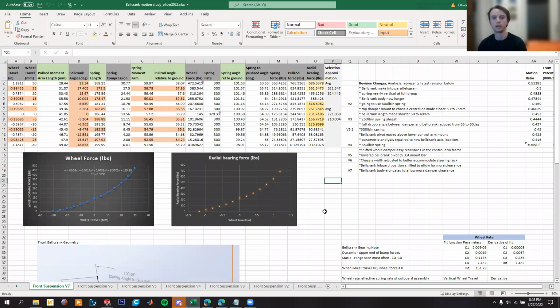damping response. So in order to reduce the amount of tilt in the car between front and back, we can tune the front and rear suspension offset from each other with regards to their damping response, so that we don't get a uniform oscillation which shakes the car. So we can make that more comfortable for the driver, but that's stuff that we'll figure out in testing. So we have that adjustability built into the suspension system.